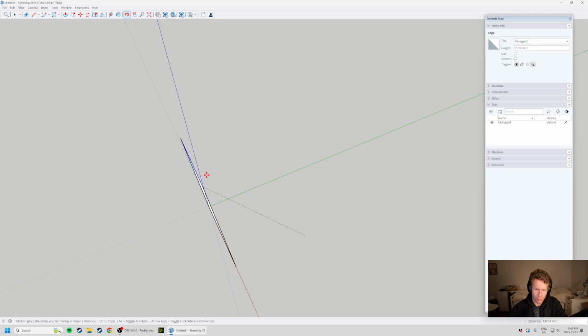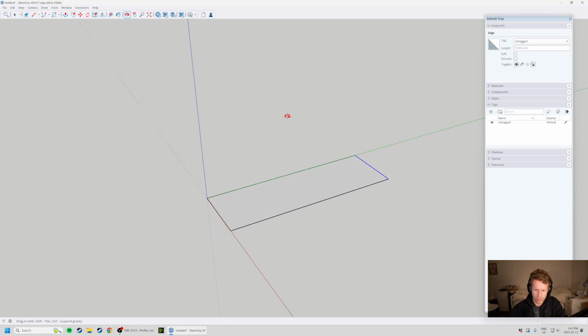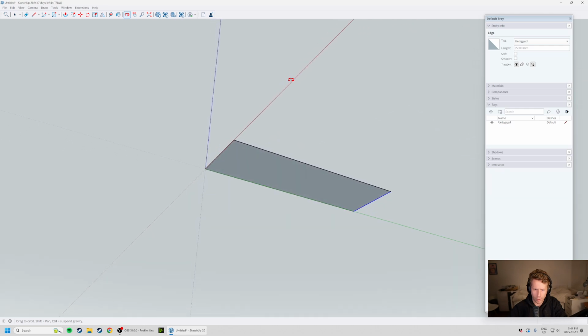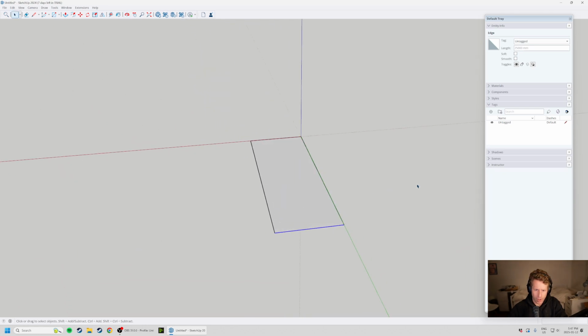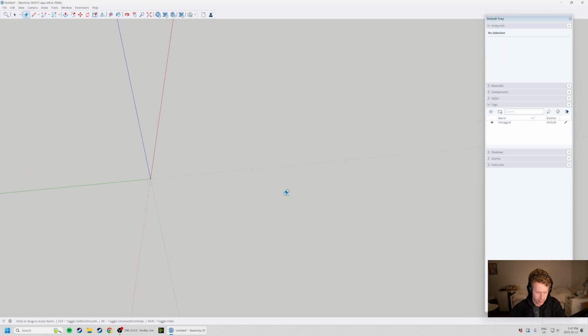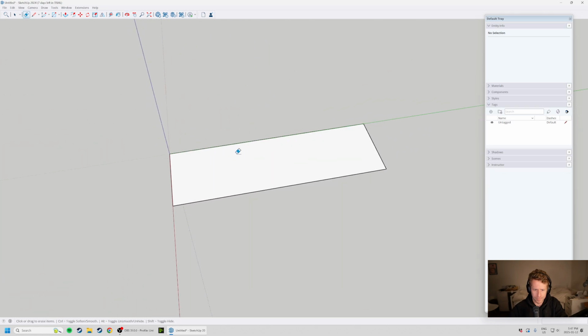So what do I really want to do here? I'm probably just going to try and drag it out to 50 meters or so, right? So let's do 50, and I hit enter, and I know that I'm locked on the green axis because it's highlighting green. If I hit enter, spacebar, and now I can start to see, if I hold middle mouse button, I can orbit around. I can come underneath it. I can come on top of it. I can spin around the object. Again, if I get lost, if I'm in the middle of space, I am going to hit my zoom extents button up here, and it's going to bring me back down to the real world.